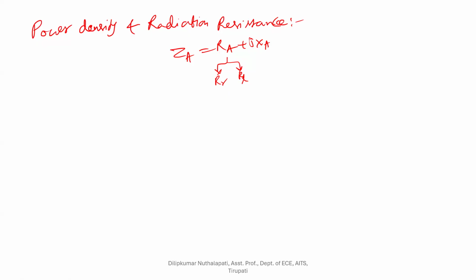So for the power of this Hertzian dipole, we use the complex Poynting vector, that is P is equal to E cross H. The average value of the Poynting vector, we can consider P is equal to 1 by 2 into E cross H star. Star represents the complex conjugate. Both E and H are always perpendicular to each other, they are not in the same direction, and the propagation of those two will be perpendicular. We have transverse electromagnetic nature here.